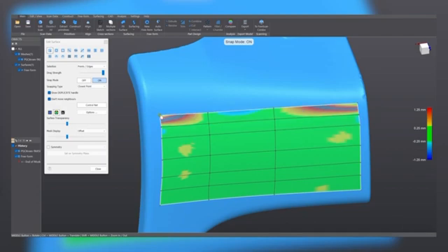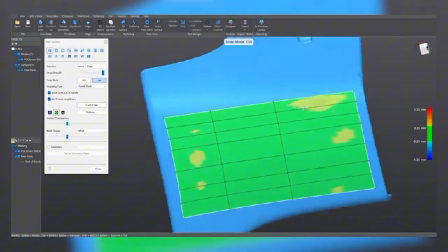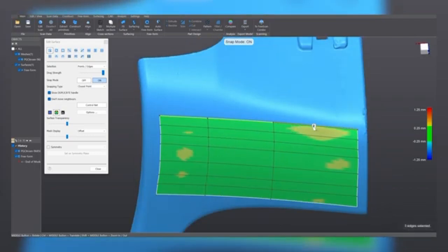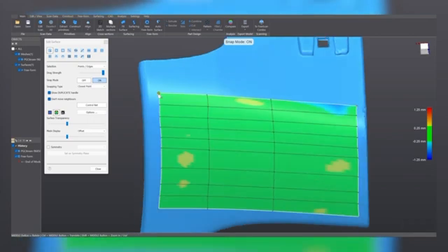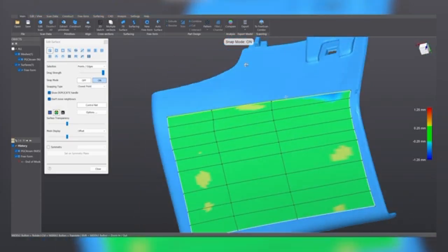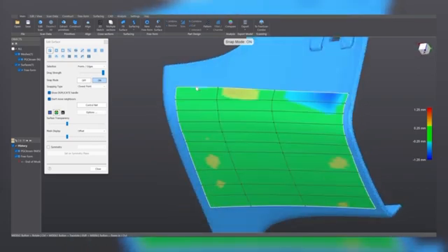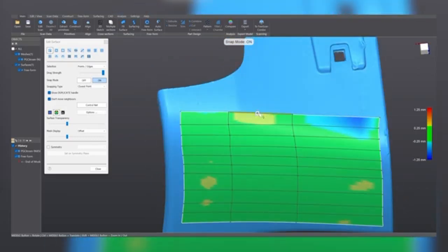Here I'm doing shorter faces because the curvature is higher on this point of the mesh. And it's a matter of selecting the edge, extruding it, letting it snap onto the mesh, and repeating. Of course, correcting at each iteration if necessary. Well done. Another short face. Good. And now that the mesh transitions to a smoother shape, we can do a little bit longer faces.